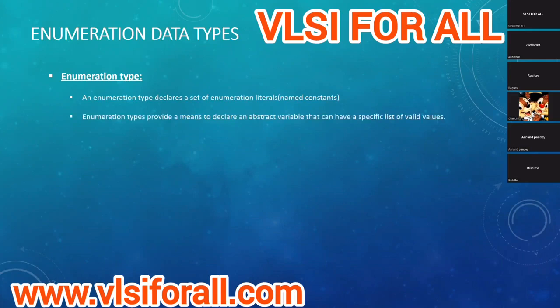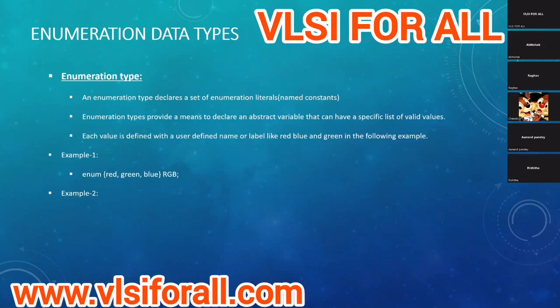So the enumeration data type is mostly used, as I have seen in the industry, in FSM states. In an FSM, you can declare different states as 000, 001. But imagine a designer has coded an FSM with 000, 001, and the next designer who replaces him comes along. Will he really understand what that state means? So you want to use enum data types: red, green, blue. You'll understand the intent of the design.